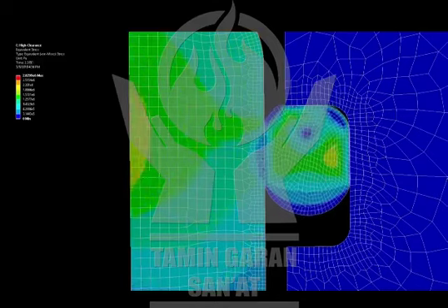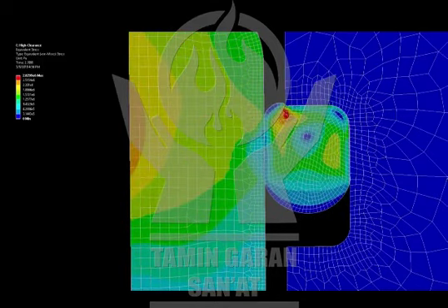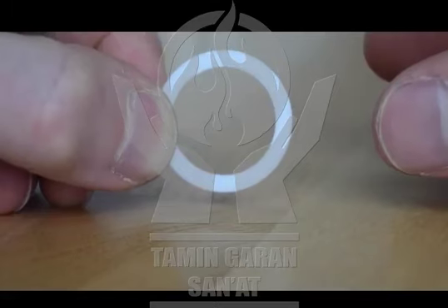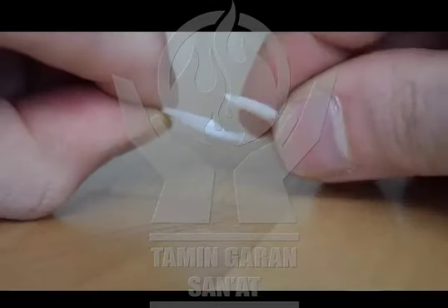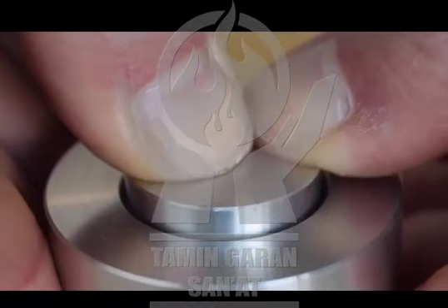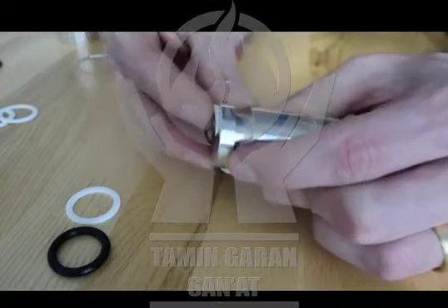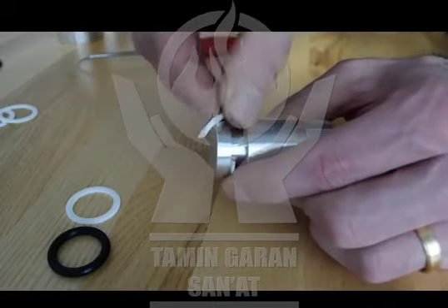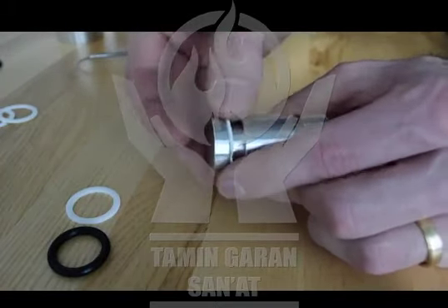The biggest weakness of radial O-ring seals is that the clearance between the components creates a path for the O-ring to extrude due to the pressure acting on it. Components called backup rings can help alleviate this. Backup rings are designed to spring out of the gland and block the extrusion gap. Where an O-ring alone could withstand perhaps only 2,000 psi, a backup ring can help it hold 5,000 or more. Backup rings are very cheap and effective.